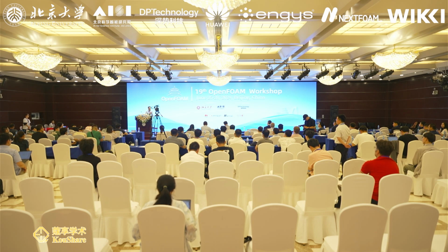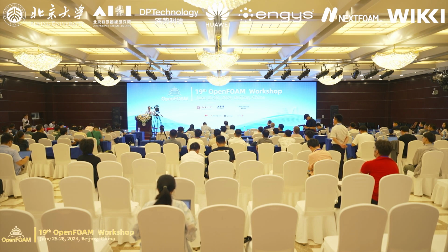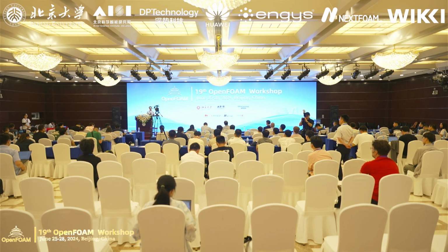Okay, thank you for your question. First, the power of our lasers is in units of gigawatt per square centimeter. This power is actually so high that, well, we do not have the presentation here anymore. But at the beginning, when I was talking about the physics of laser shock peening, I said there is some ablative or sacrificial layer on top. The way it works is basically that the sacrificial layer is evaporated instantly.